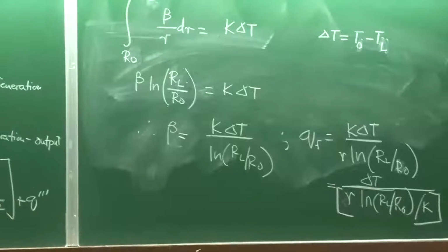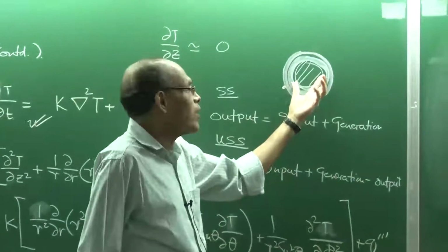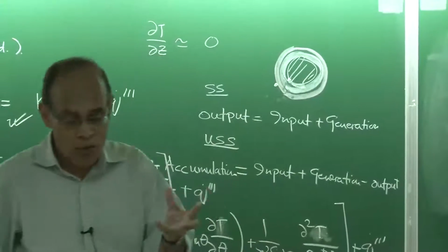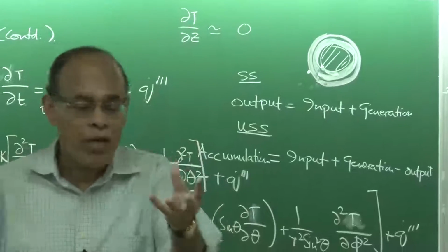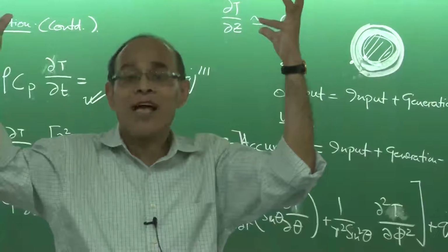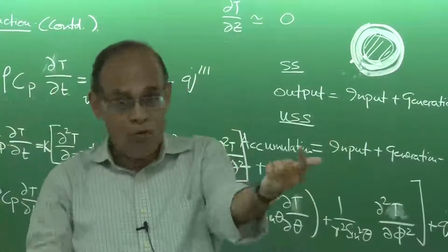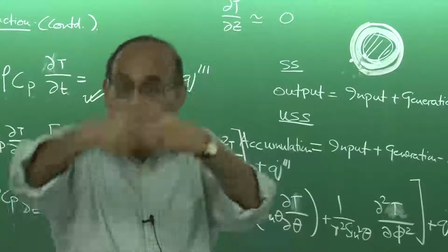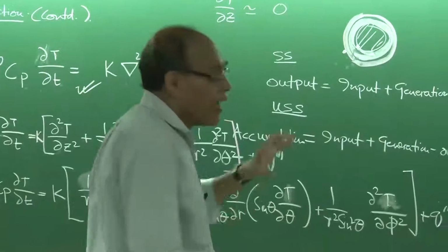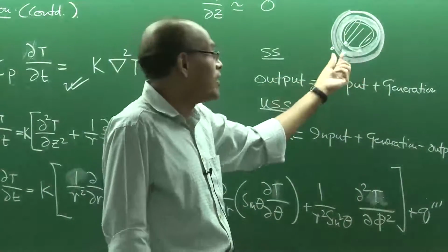We will solve some problems, and then you will have practice on how this typical problem is very important in the context of, say, flow. Something is flowing, hot fluid is flowing through a pipe, and then you have certain insulations. You have seen maybe a split AC, for example, the outside pipes, okay? Those pipes through which the cold air comes from the outside machine into the house are coated with first maybe a layer of adhesive, or some kind of tape, and then some kind of an insulating material layer.